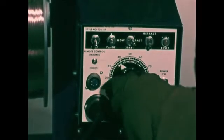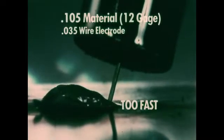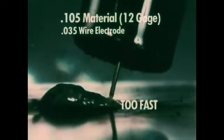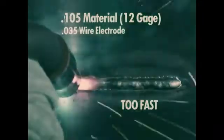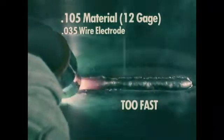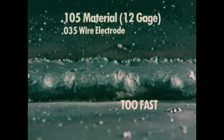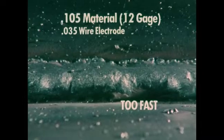Now the wire feed speed is set too high. The welding condition is very erratic. Examination of the weld joint shows a great degree of spatter. The bead is narrow and ropey, with a high crown. This would suggest an excessive amount of filler metal for the joint, and that penetration is likely to be poor.